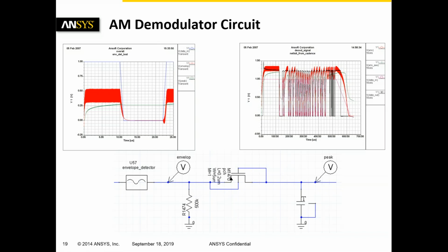It is then compared with an average output of the envelope signal to produce the digital output stream. The figure on the top left is the result of one typical bit cycle, where red is for the envelope signal, green is for the average value, and blue is for the output. The curves on the top right are for a more realistic case.